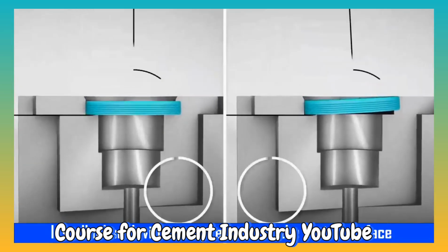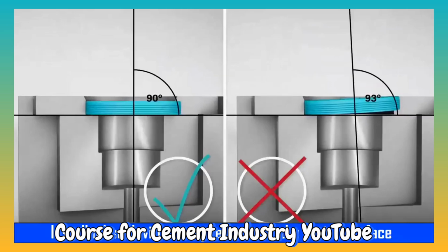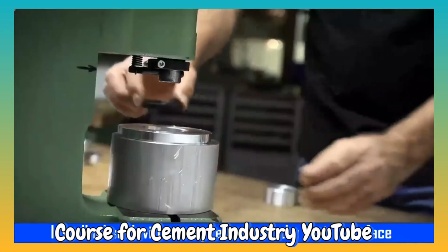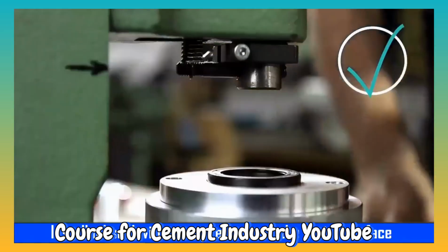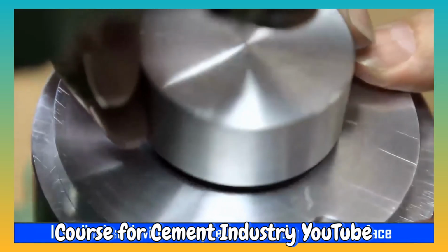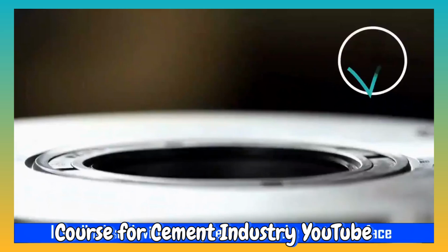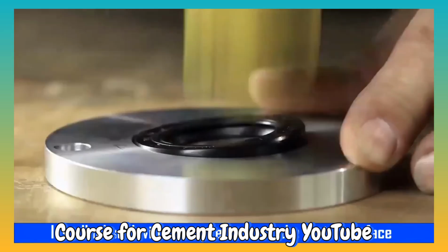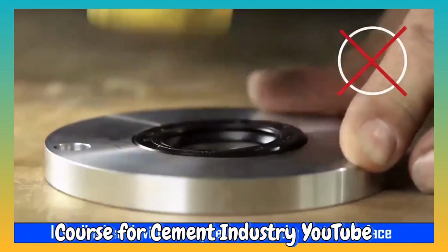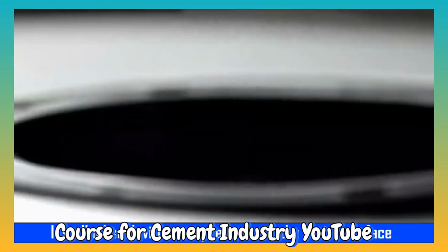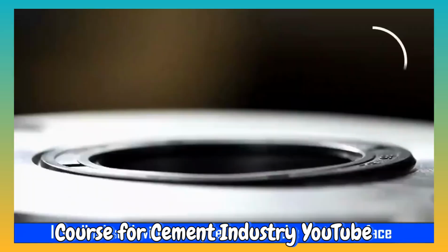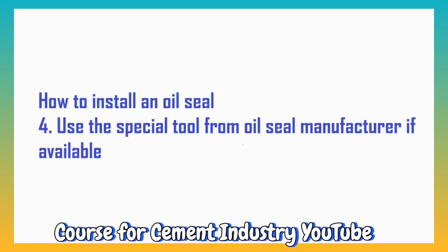Make sure the oil seal is installed perpendicular, at 90 degrees to the axis of the shaft. If available, install the seal using a special press machine. Do not use the hammer directly to hit the seal as the pressure is uneven. Check seal surface flatness after installation. Use the special tool from the oil seal manufacturer if available.